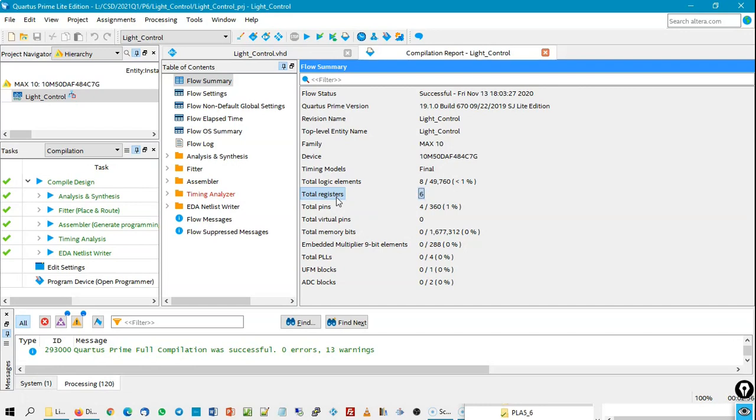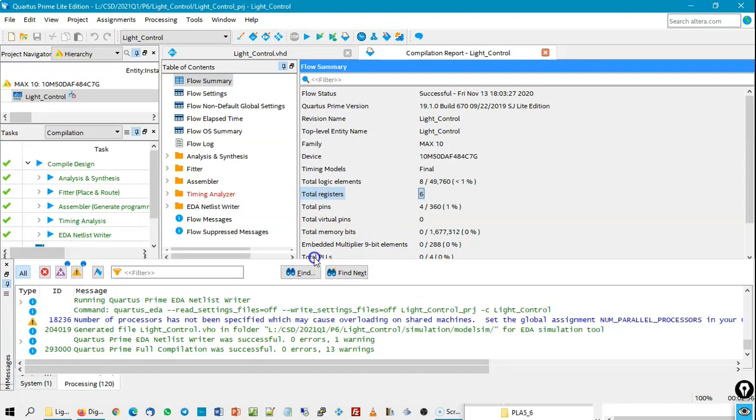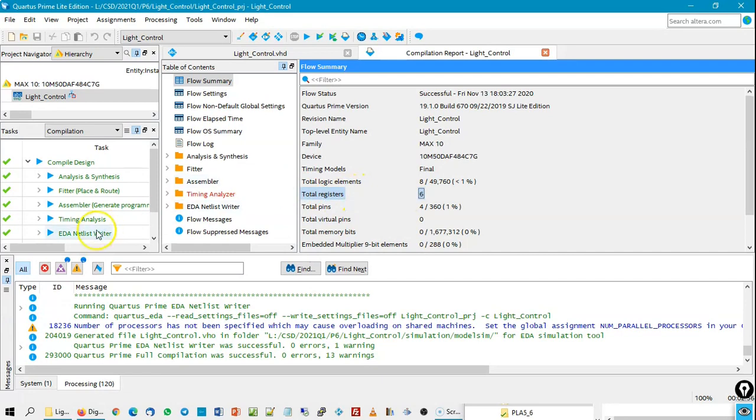You can do it in another way, choosing, for example, binary or gray, and in that case, you know from the plan that the number of registers has to be only 3, because using 3 bits you can encode up to 8 different states in binary. But this time, the number of registers is 6. So let's inspect before making any change here or recompiling with other parameters.